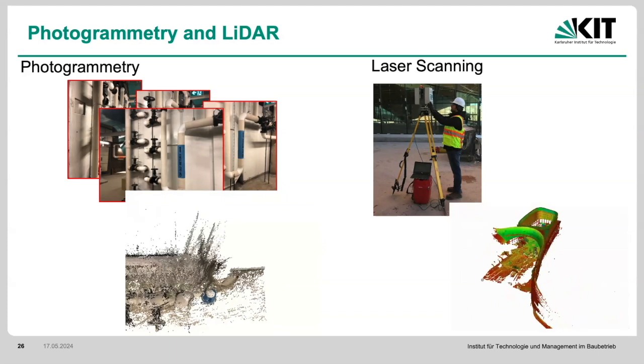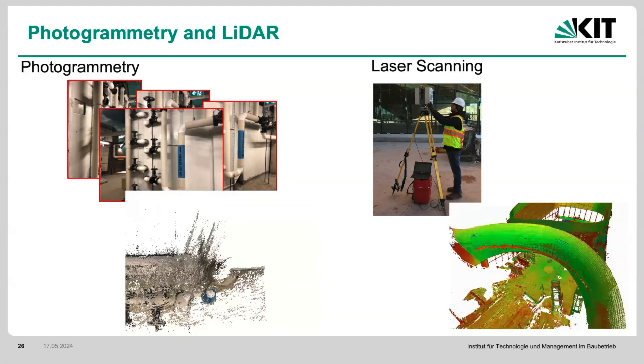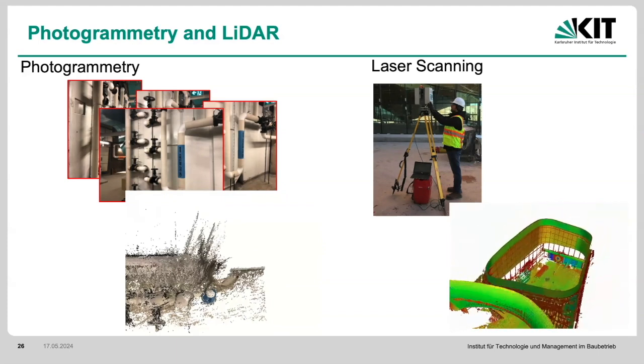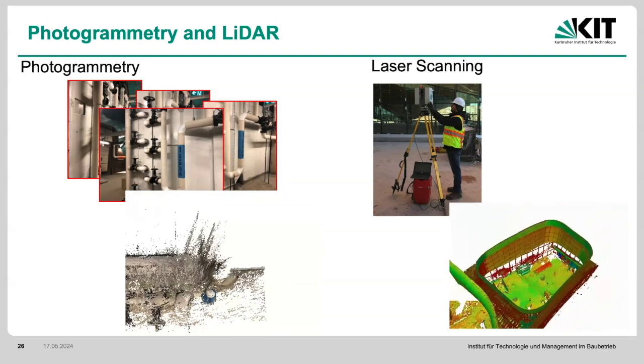Now we have mobile laser scanners as well, meaning that it's kind of something similar in between that you can put, and it emits laser signals, light signals, and it reflects off of the surface and directly gets the 3D measurements there. And then you can use something similar to the structure from motion to get the orientation through what we call simultaneous localization and mapping, SLAM.